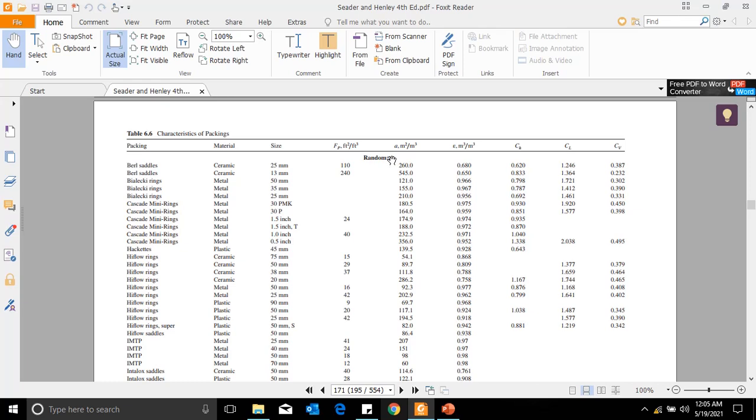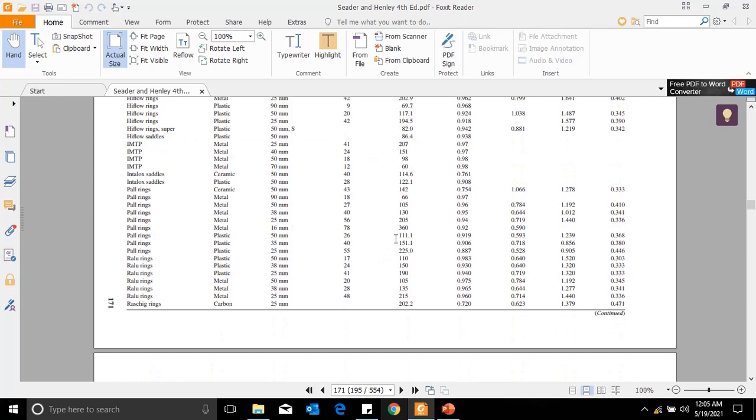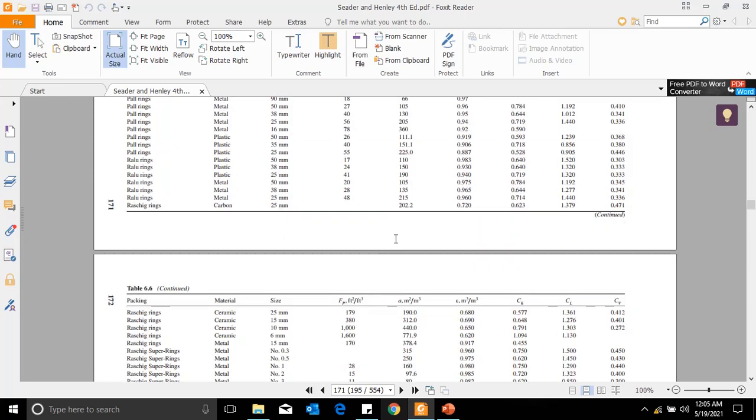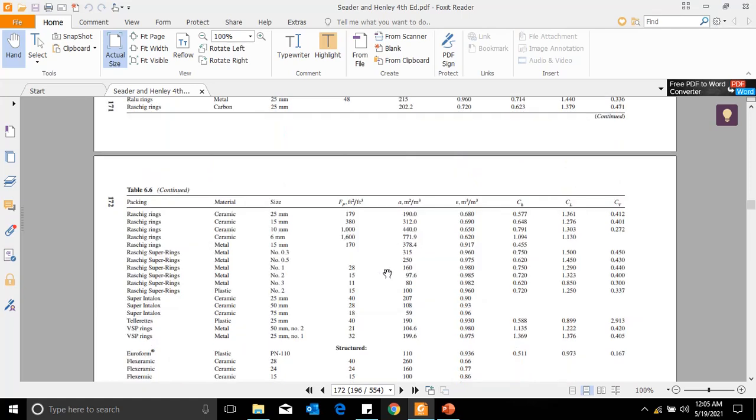Later on, being a design engineer, for example, you have to present a solution for some specific separation. You can select either random packing or structured packing, compare a number of parameters, for example the required diameter as well as the pressure drop inside the tower and so on, and then select one specific solution which is good or suitable.